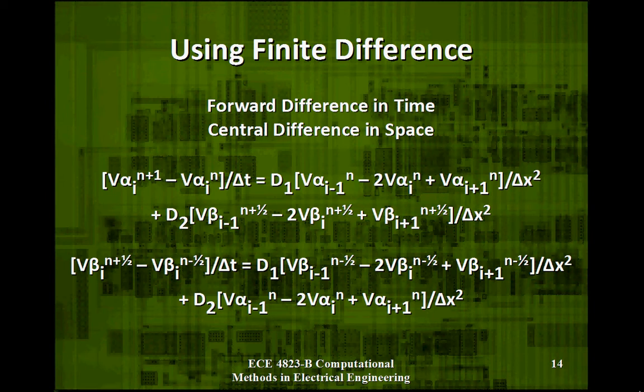As an aside, solving the crosstalk equations with an explicit numerical method like the one proposed will necessarily limit the values for R and C that will produce a stable solution for a given delta x and delta t. The Crank-Nicolson method might be a possible implicit alternative. Now that the method of solving the system is developed, let's take a look at what we can find out using MATLAB.